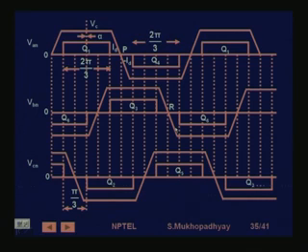manner that whenever the induced EMF is positive in that phase, we will try to drive current through it, because we know that we can generate positive torque if we drive a positive current for a positive voltage. So, we will be delivering power into that phase, and that phase will experience the torque, and the machine can